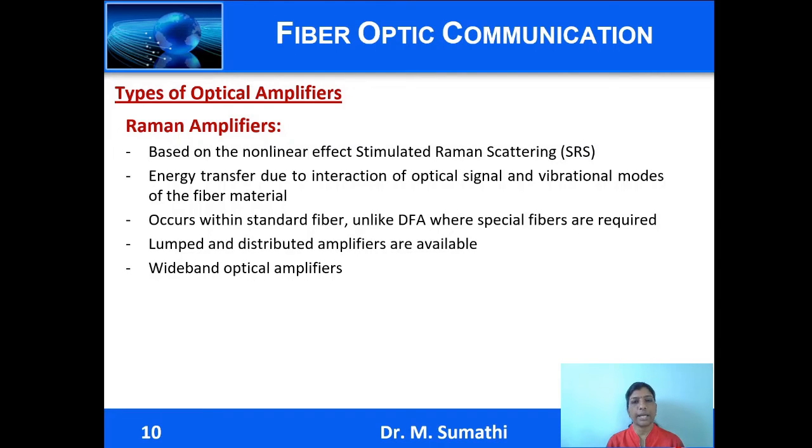These amplifiers are based on the nonlinear effect of stimulated Raman scattering, or SRS. We have already discussed this in detail in the previous video on nonlinear effects. So here there is no stimulated emission. The energy transfer takes place due to the interaction between the optical signal and the vibrational modes of the molecules of the material. So a pump signal interacts with the material and the energy from the pump is absorbed and transmitted as energy at a longer wavelength. This wavelength is called the Stokes wavelength. So energy from a shorter pump wavelength gets transferred to a longer Stokes wavelength, and the energy difference appears as molecular vibrations in the material.